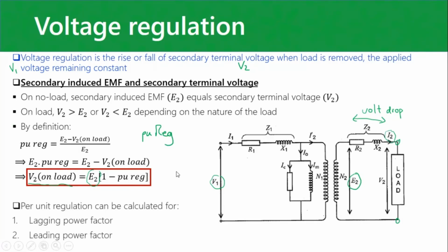So we have to take into account that this load could have a leading or a lagging power factor. In other words, a lagging power factor would be an inductive load, so it's probably more likely to be this one. But let's say you have a capacitive load, you would have a leading power factor, because the power factor with the transformer is set by the load. Phi 2 is set by the load all the time, not by the transformer.